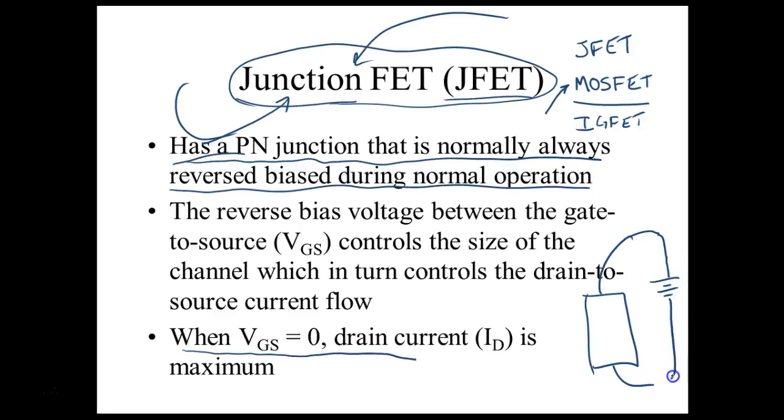As soon as I did that, we would have current flow, because there's a semiconductor and there's a path through there. So the current would flow through the JFET all the time. That means if I took an ohm meter and put it between the drain and the source, it's going to look like a resistor. It's going to have a resistor value.